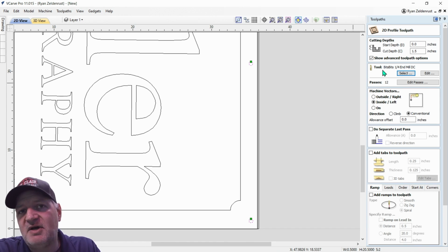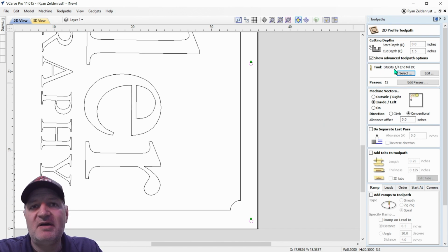Now look, I'm using an end mill. Some of you are going to say, oh, but you're using a 1/4 inch end mill to drill a hole. It's not supposed to be used to drill a hole, and you're using a down cut. I mean, optimization would be to use an upcut bit here, clear out the chunks, but this is one cut, one quick hole. It's not going to start a fire on these two little holes. Yeah, it's going to be fine. It's not going to be a big deal. You'll see there won't be any smoke or anything when I cut my holes. It's just if you're making a bunch of holes, it can heat the bit up. It can heat up pieces quicker. Then you can get a fire. Making 1 or 2 holes, you're going to be fine, especially if you have a new sharp bit.